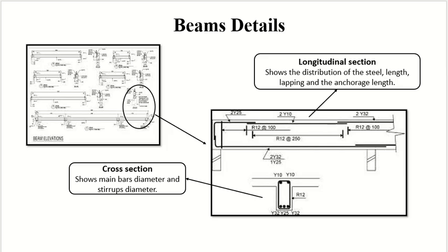Okay, if I cut a longitudinal section, what am I most interested in? Which part of the column am I most interested in? The start and end. Very good. Why? Because we have the reinforcement connection. Connections, yes. The most important element of the cross sections and the detailed drawings is the connections, and obviously the reinforcement is part of it. But you will see in these drawings, wherever there is a connection, we go into more detail.